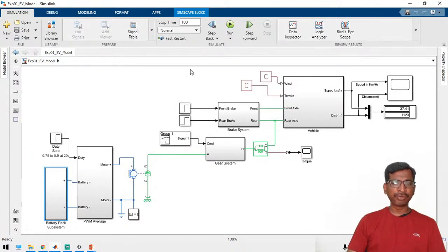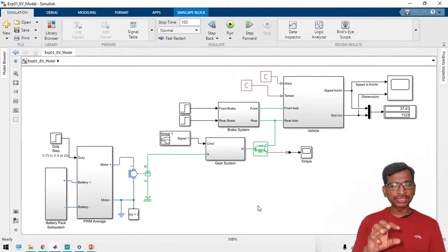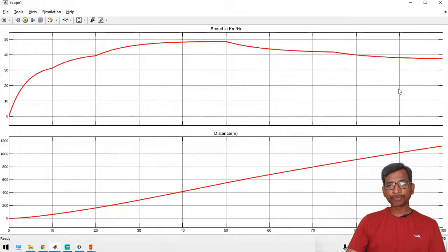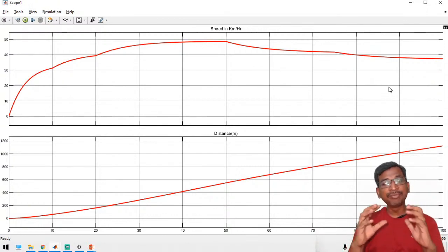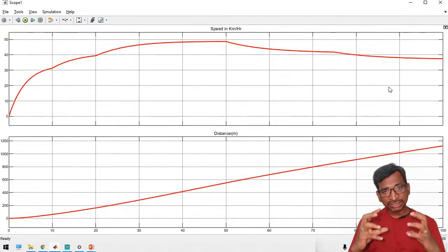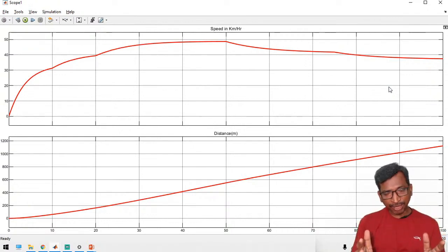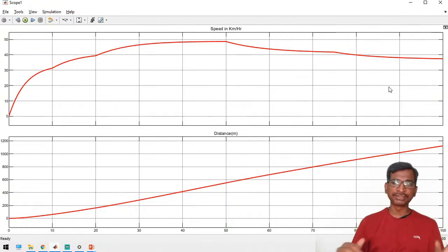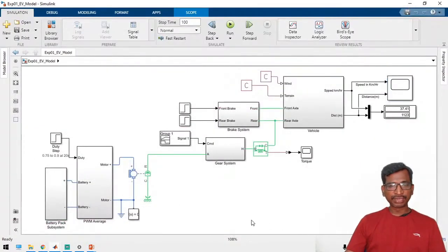If we apply this DC voltage, we are going to run this vehicle with 3 different speed levels and then braking mechanisms. This all comes under open loop, not closed loop systems. If you run this simulation and power up your vehicle, due to the gear mechanisms the 3 different speeds are applied, and after that, due to the braking mechanism, 2 levels of braking are applied. These are just system verifications, not the final project. From this point, we have to integrate all these things with the drive signal.